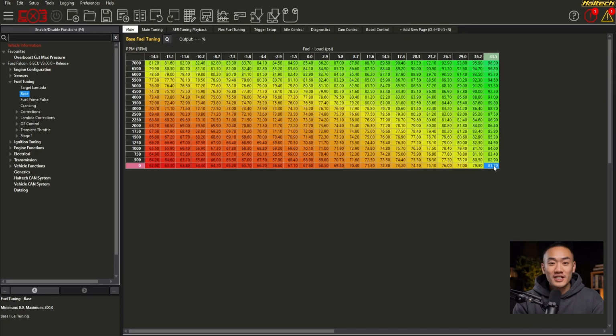If a turbo engine is only showing 40 or 50% VE at full boost, but lambda is correct, that usually means airflow is being underreported and the VE table is compensating heavily. On the other hand, extremely high VE values across the entire map often indicate that the ECU is being forced to add air mathematically because one of the airflow inputs is wrong.